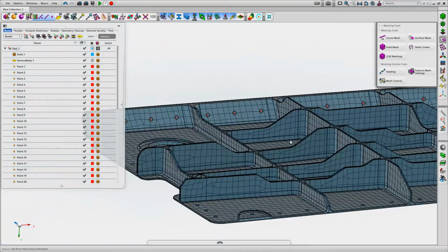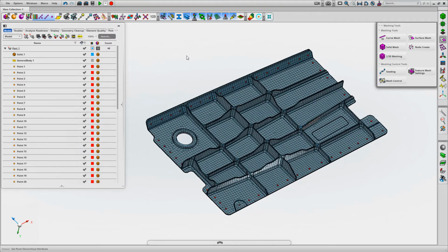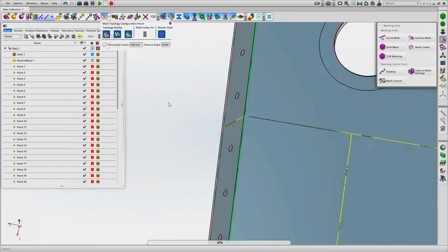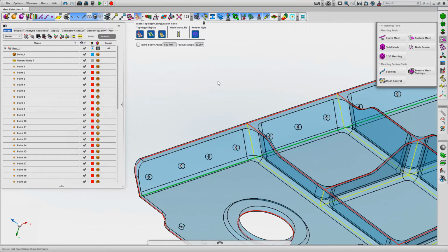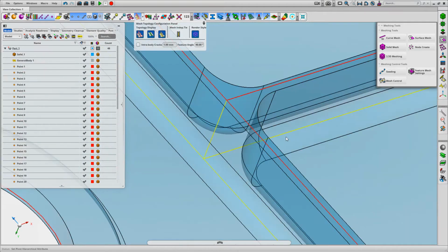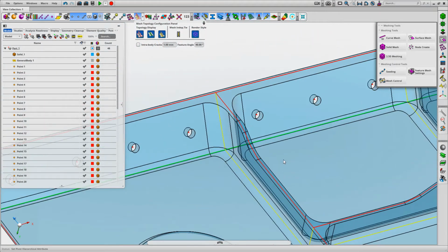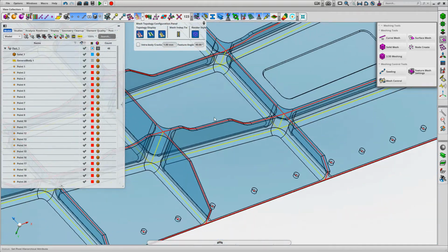One thing I didn't look at, which we can do now, is to look at the mesh topology. We looked at the geometry topology, the edges and the like. If we look at the mesh topology, we can see where the free edges are relative to the solid. If I hide the underlying surfaces, there you go, pretty nice definition. The coloured lines, the red, yellow and green lines, all relate to the underlying shell mesh versus the transparent view of the solid CAD model.